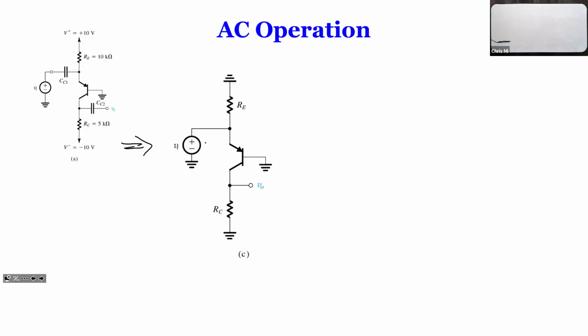You obviously have to connect voltage sources here and there, okay? So the important thing here, of course, there's no need to do this step. You can actually go from there directly to a small signal, okay? So this step is not necessary. But sometimes students get really good at doing problems. They don't do the small signal model anymore. They simply do this. They don't draw the actual control current source, and so it's okay. As long as you can manage that, there's nothing wrong.